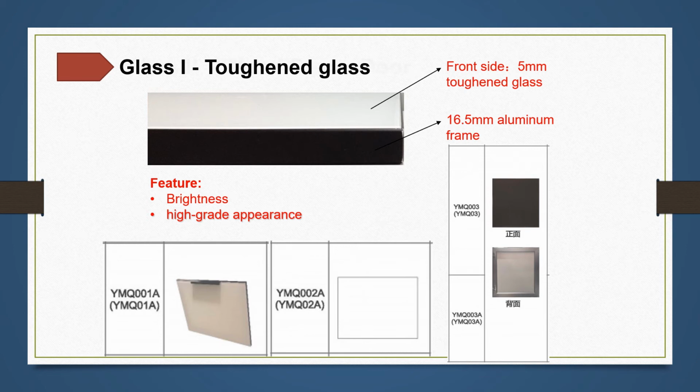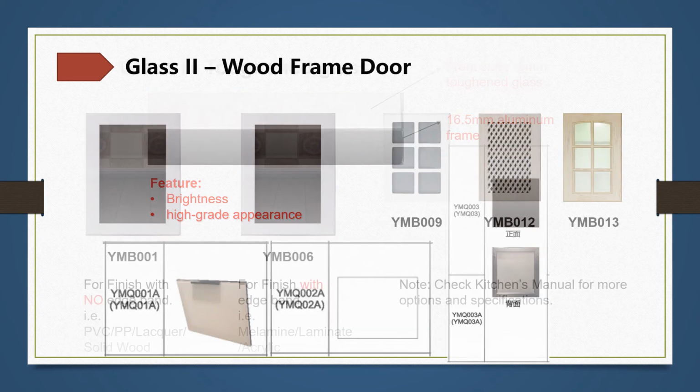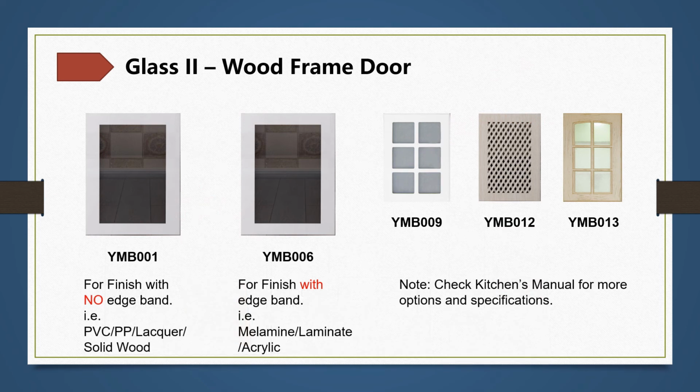PP has a deeper and harder texture that is often viewed as a good substitute for solid wood. The production process of PP covers the 4 edges of a panel like a roller, including the front and back sides and 2 edges, leaving 2 other opposite edges uncovered. For all PP doors, they will be in frame structures, and each side of the frames will join at 45 degrees with the other sides and get its uncovered sides joined together. So PP doesn't need an edge band either.